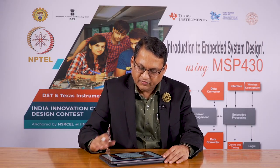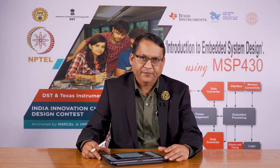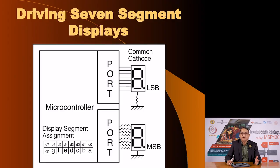Here is another variation. Now, you may wonder that instead of connecting using 8 resistors, can you use a single resistor like this, and this way you can save 7 resistors? Well, this may seem like a good deal, but this will give you unequal intensity of the LEDs. Now, imagine that you want to turn only one LED on, maybe you want to just display a bar. So, this particular LED you want to turn on.